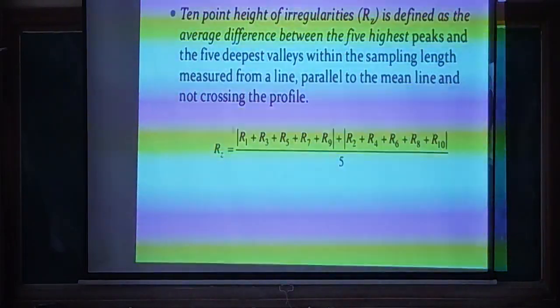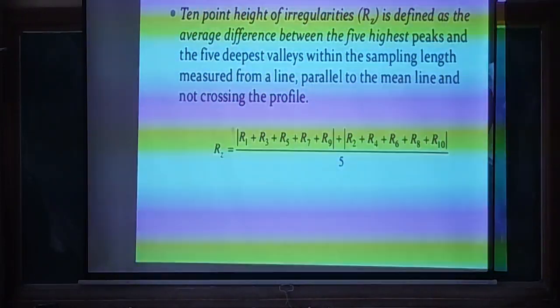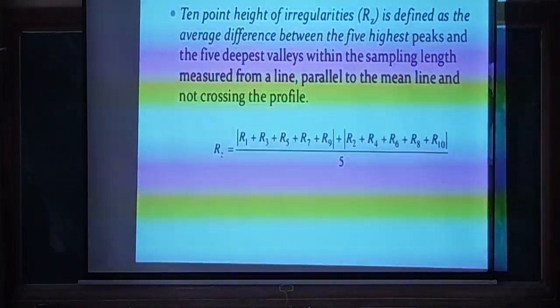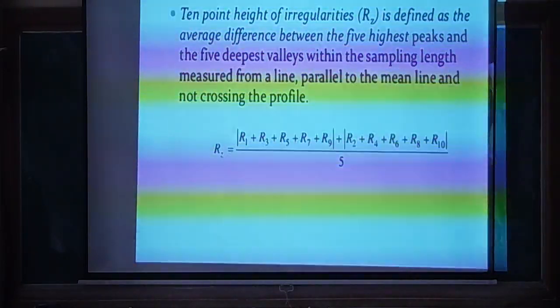The length is measured from the line, from where we are starting, parallel to the mean line and not crossing the profile. Whatever profile we are selecting, the line should not cross the profile.